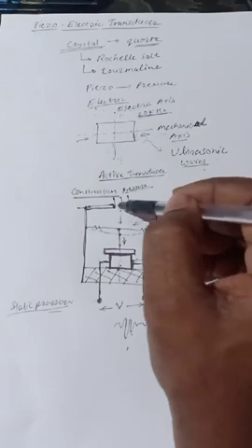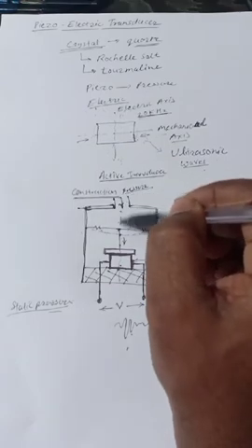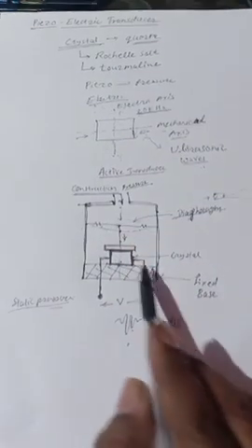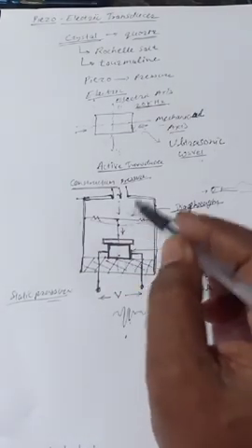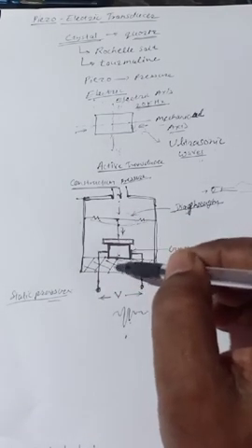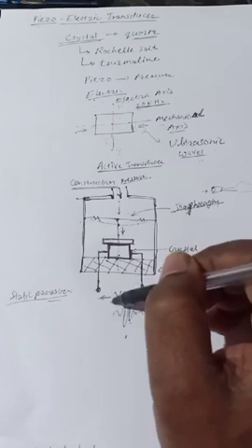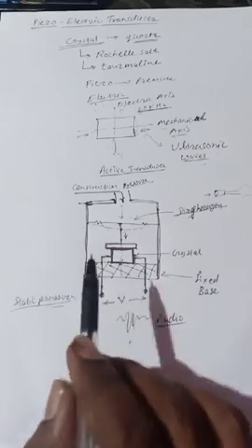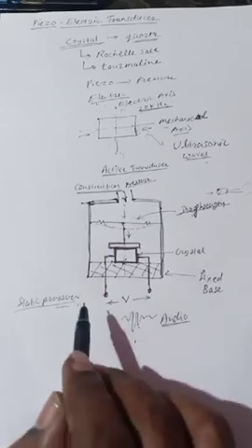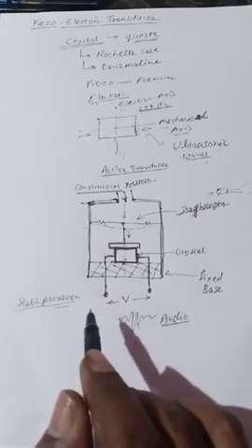Okay, so when there is a constant pressure from this side, then it cannot be detected by this signal because it requires a variable pressure. So this is the disadvantage of this crystal. It cannot measure static pressure. So you have to keep in mind that. But the capacitive transducer can measure static as well as dynamic pressure.